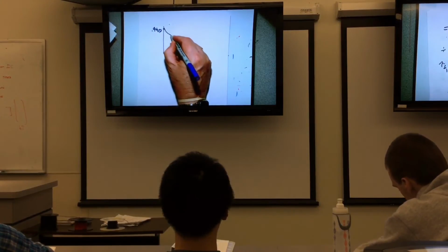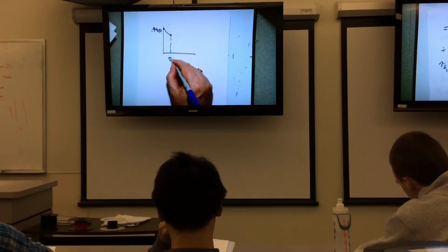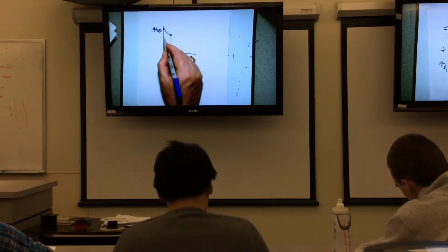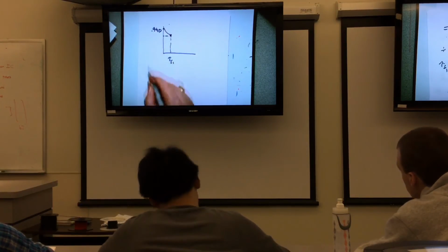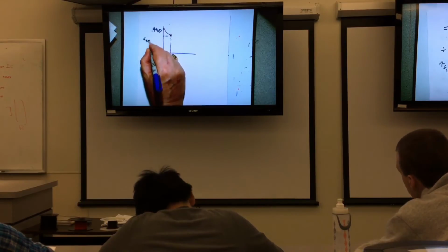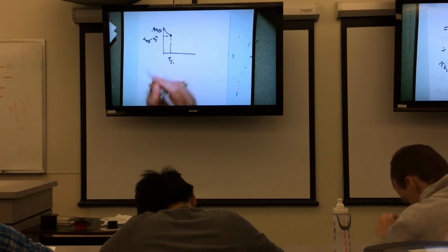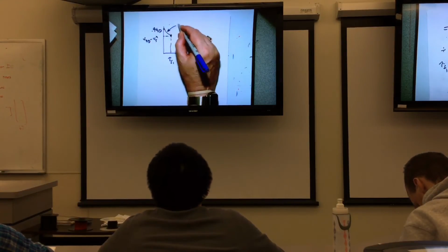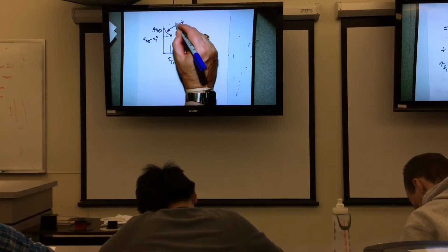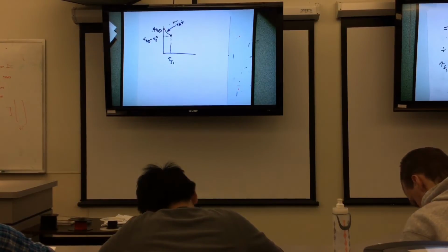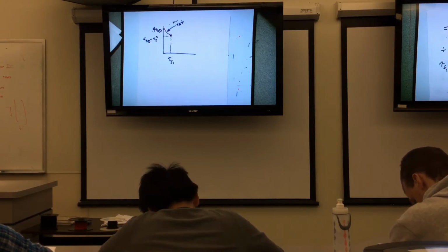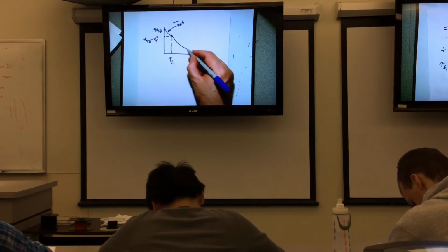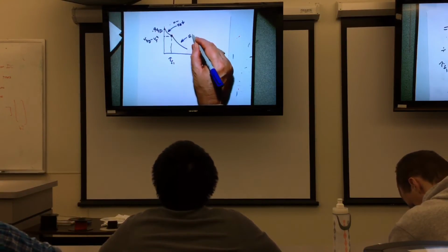And we descended during this first piece to this other voltage, which is VDD minus V threshold N. That's when we're in position. This was the saturation portion, the saturation discharge. Okay, and then we switch over and we're going to run the rest of the way on active.